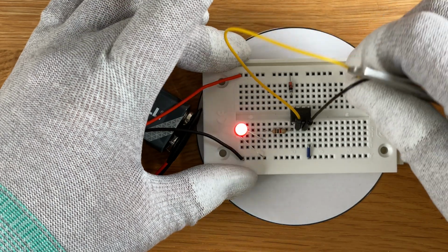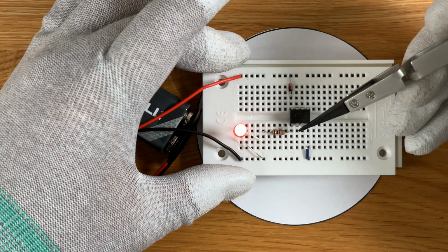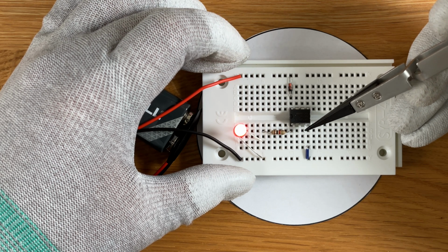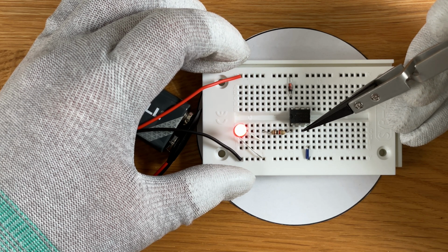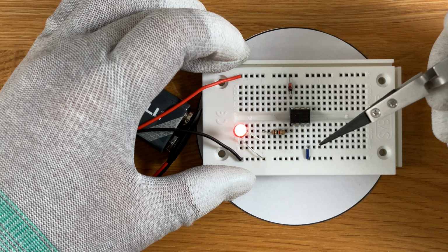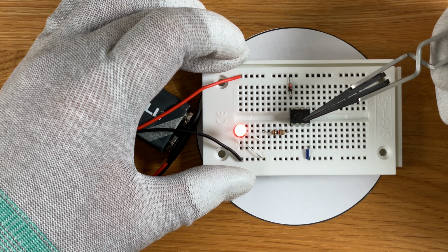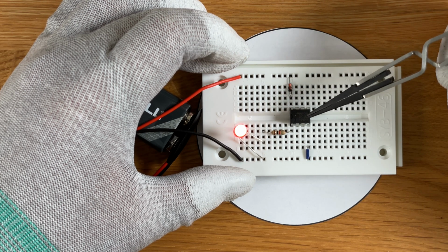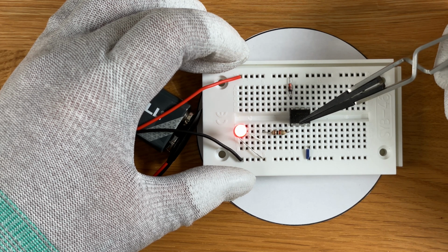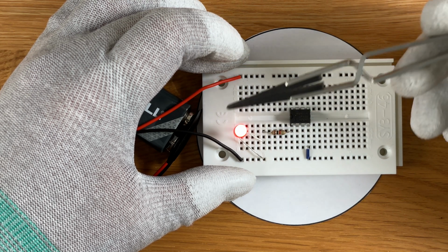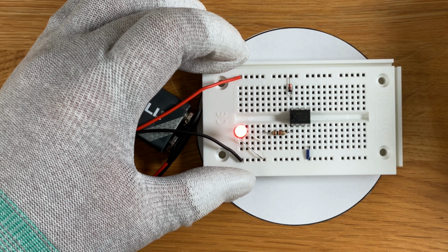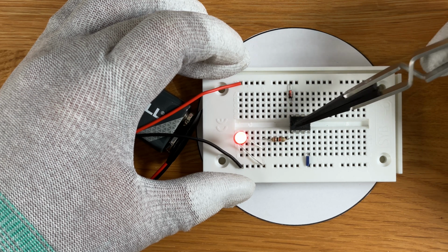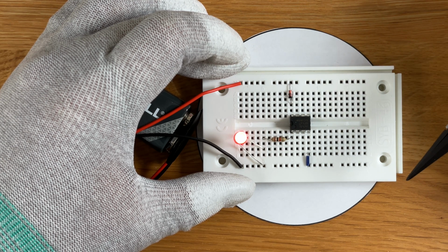In practice, in one of the next videos, we will connect these input pins to a sensor and a Wheatstone bridge, which is used in order to generate comparative voltage values based on light intensities. And this is going to be a slightly larger circuit where we use a comparator, an operational amplifier as a comparator, in order to compare the ambient light to a reference value. And this is going to be very useful in order to switch on the light as soon as the ambient light on the sensor falls below a given threshold. This is one of the primary use cases of a comparator. Compare two voltages and trigger an output once it's above a certain threshold.